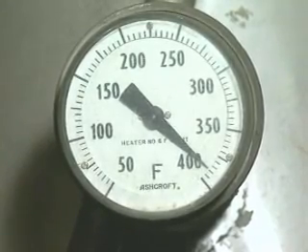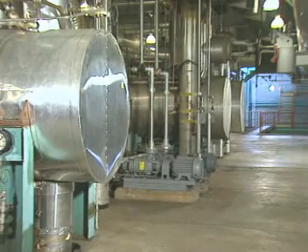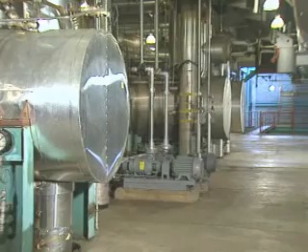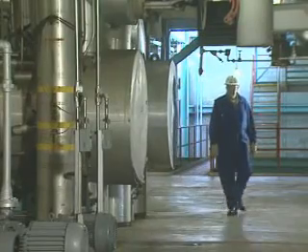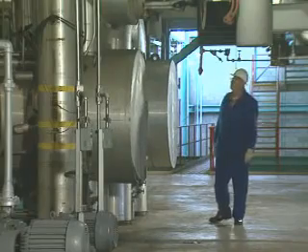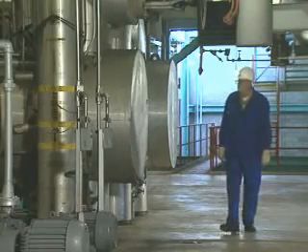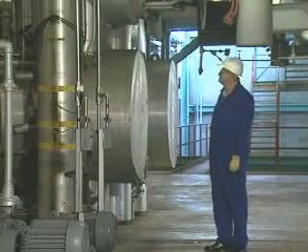Checking this temperature is the quickest way to get an overall picture of how well the feed water heaters are doing their job. If the final feed water outlet temperature is at the expected level for the given load, then each of the feed water heaters in the train is probably transferring heat at the proper rate. But sometimes a heater within the train may be transferring heat at an improper rate, even though the final feed water outlet temperature is at the expected level. So periodically, you should also check the outlet temperature of each heater in the train.